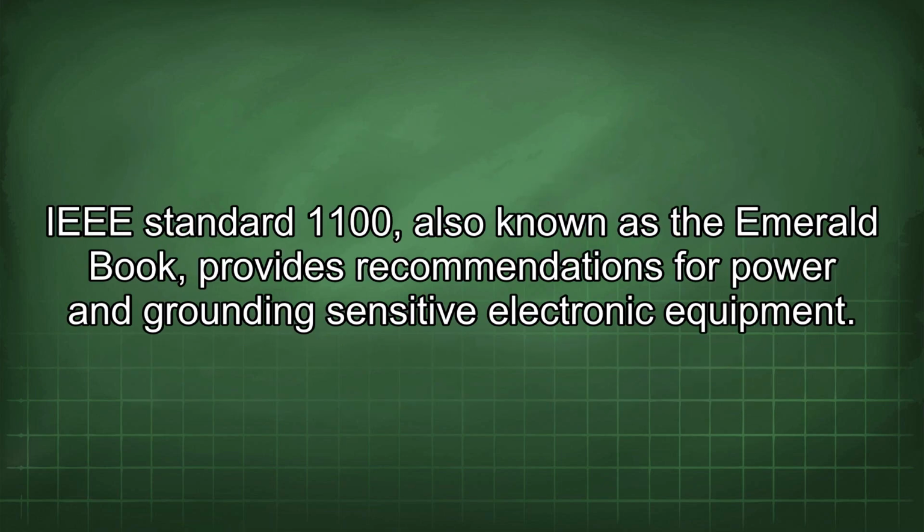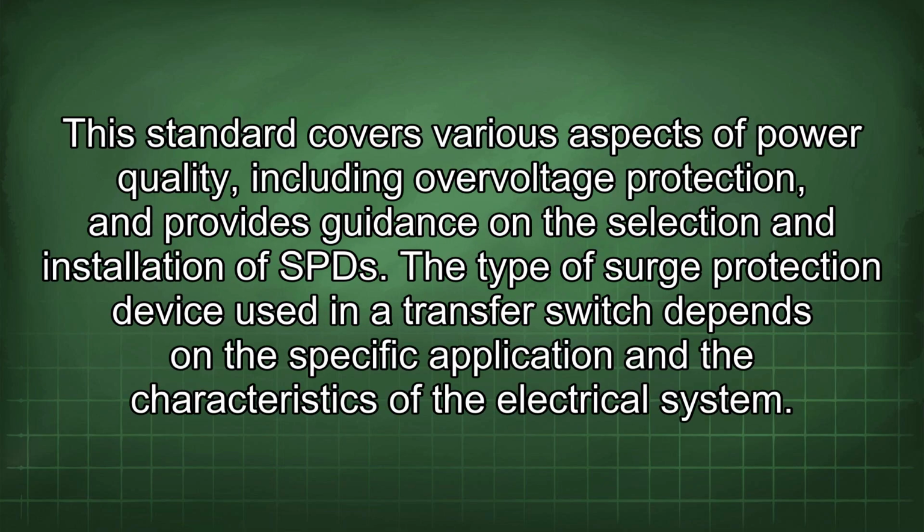IEEE Standard 1100, also known as the Emerald Book, provides recommendations for power and grounding sensitive electronic equipment. This standard covers various aspects of power quality, including overvoltage protection, and provides guidance in the selection and installation of SPDs. The type of surge protection device used in a transfer switch depends on the specific application and the characteristics of the electrical system.